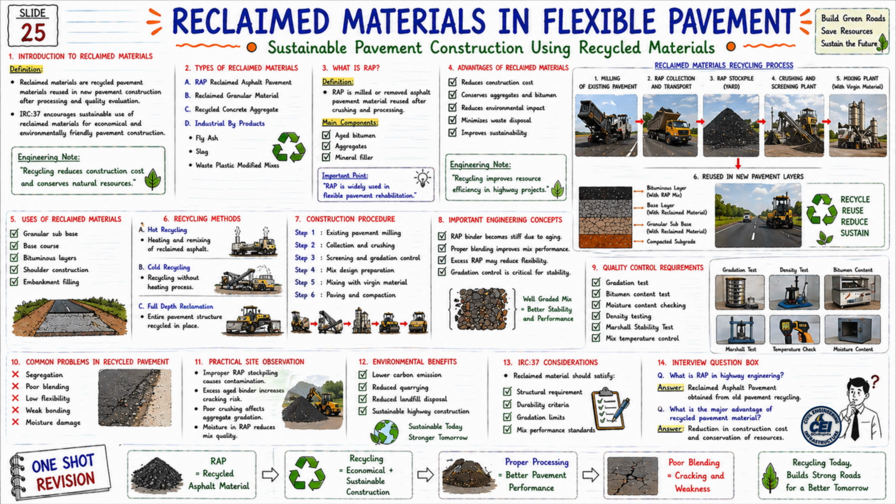Now let us look at the 11th topic. Practical site observation. Improper RAP stockpiling causes contamination. Excess aged binder increases cracking risk. Poor crushing affects aggregate gradation. Moisture in RAP reduces mix quality. And these issues are most commonly seen in practical projects.